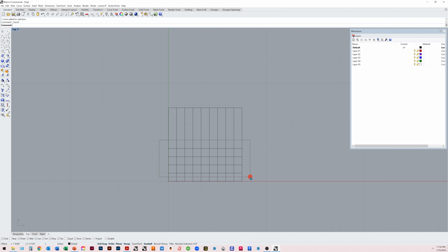If I put those lines fully inside the box, it'll select them. Now watch what happens if I start to select only part of them. Nothing works, right? So if I go left to right, I have to put the whole object in the box. Now watch what happens if I go right to left. Now it'll just select the objects that it touches, right? So I could do this and select those 4, right?